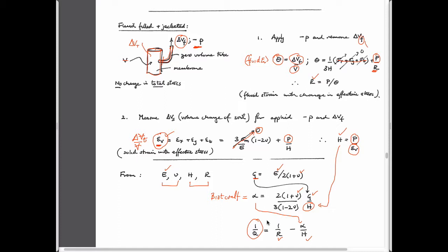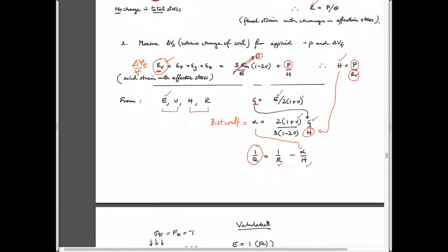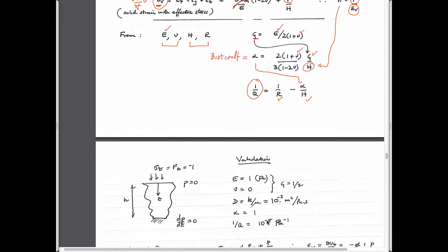And the most important part, do it dry, get the elastic moduli, which are drained behavior. Right? By definition, we're not developing fluid pressures, so they're drained, would be the terminology that's used. And then do it wet, sealed inside a sleeve, and measure two things, the change in fluid volume and the change in overall volume. And the difference in those says something about the physical system, and as we'll go back.